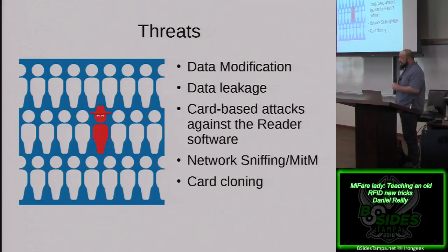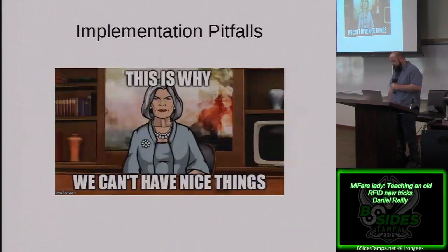This is a huge problem because even in the world of Mifare, the first sector of the card is locked. You're not supposed to be able to overwrite it. That's the unique identifier from the manufacturer. However, there are Chinese magic cards which allow you to overwrite all those sectors, including the first sector, the 0 block, which will allow any card to completely and fully emulate any other Mifare card. So we need to be able to stop that.